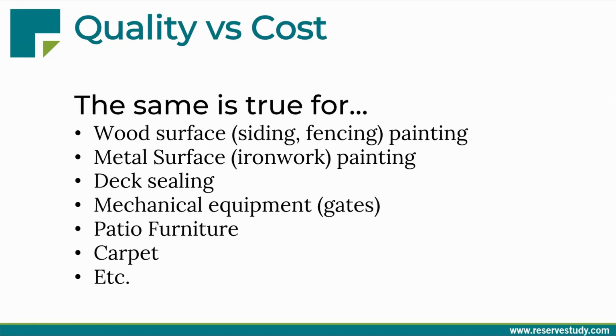And the same is true for a lot of projects. Your wood and metal surfaces on the exteriors are very vulnerable to weather elements. So the repainting and resealing of the exteriors is crucial to prevent high repair costs and to extend the useful life of siding, which is critical. Decking sealing prevents water intrusion that can cause structural damage. So ignoring a $1,000 per deck resealing project could result in a $10,000 or $20,000 per deck reconstruction.